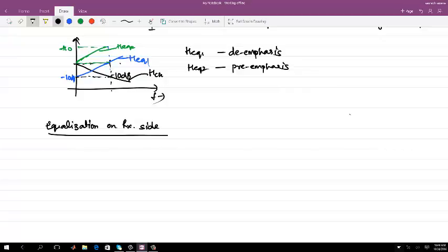So what kind of equalization have we learned? We have learned only FIR equalization on the transmitter side. Whichever way it is implemented, that is fine, but this is like delaying the signal and summing it up. Voltage mode equalization. So if you want to implement that at the receiver side, what would you do?